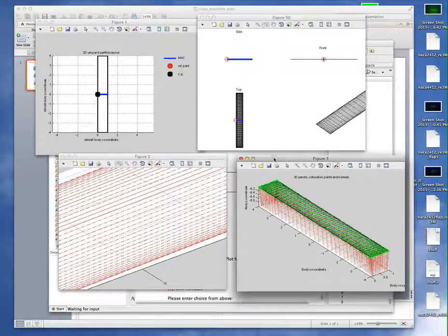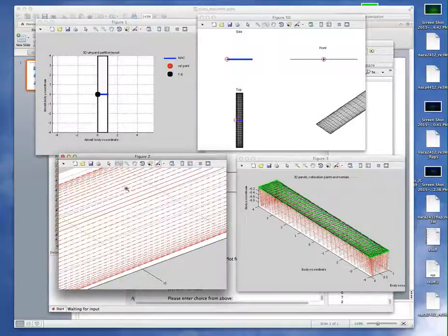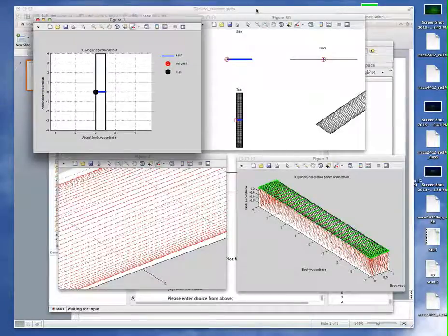So this is a vortex lattice, or a VLM method of solving. It's an inviscid boundary method where you have to consider this wake sheet and how it comes up with the distribution of this vorticity, or strength of these little vortices, in order to satisfy boundary conditions on the wing itself, done using a matrix inverse.